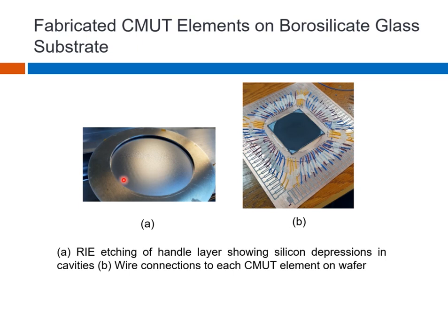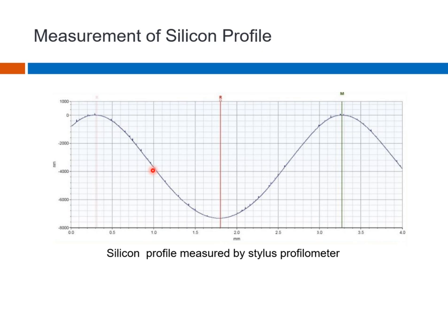If you run a stylus profilometer over here, like a Dektak, you will see that from 10 micrometer, about 7500 nanometers has been depressed by the ambient pressure, which shows that the plate is not collapsing on the substrate. It is still hanging because of the air pressure that we have outside of the evacuated cavity. Okay, so they are uncollapsed CMUTs by design.